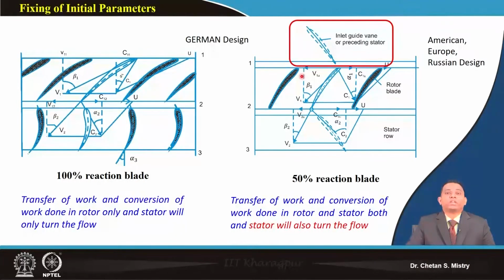When you are doing design for a particular stage, be careful: for later stages, say maybe third stage or fourth stage, we can move with a 50% reaction design configuration, and that is what will be giving this inlet guide vane. So initial stages you will not be going with 50% reaction, and later stages you will go with 50% reaction design. Okay, so this is a design philosophy, and when you are doing your design, you will learn all these aspects.